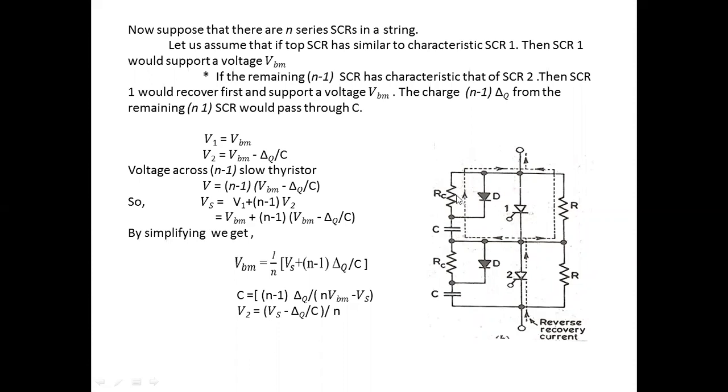Here, this capacitance has the effect of removing the inequalities in thyristor self-capacitance. It can be discussed like this: during the turn on and turn off time periods, the resultant of the shunt capacitance and the self capacitance of each SCR tends to be equal for each of the series connected SCRs.